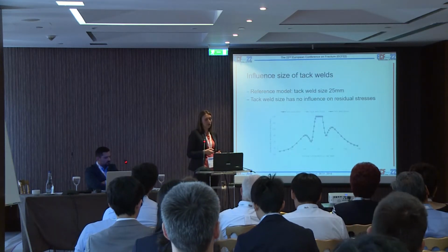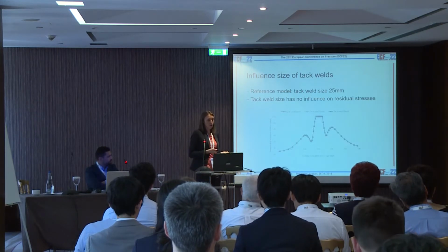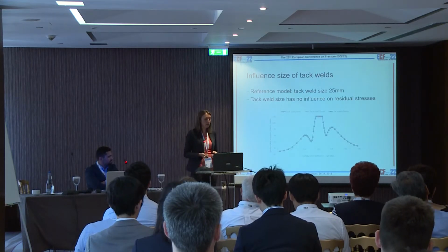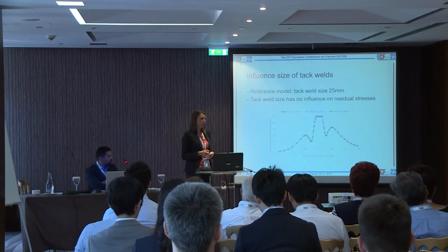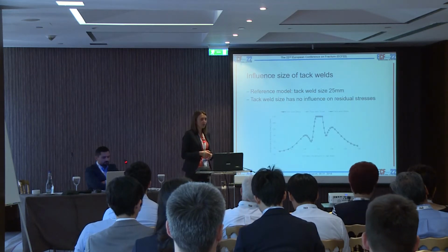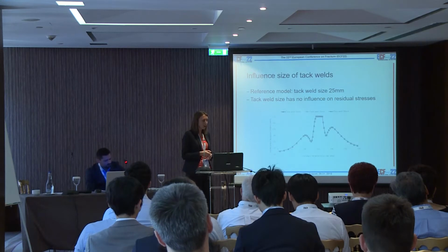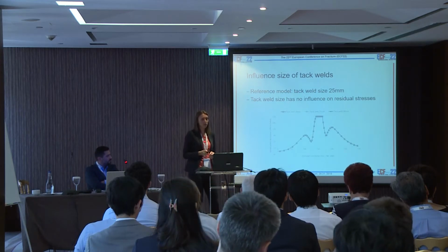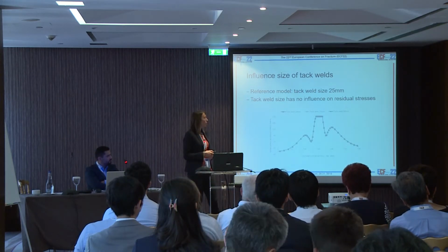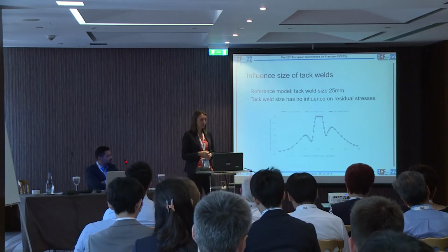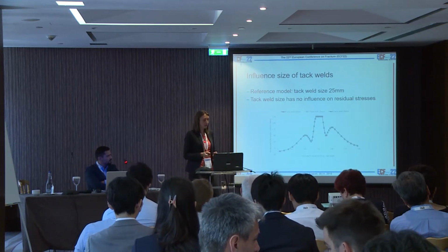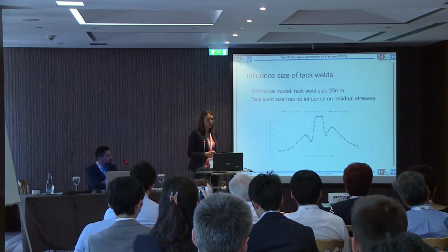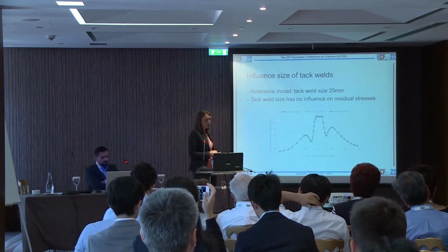Now we have this residual stress distribution from our reference model, but we want to see whether we can reduce the tensile residual stress zone in order to prevent the cracks from opening faster. So we did some variation of different parameters, and the first one was the size of the tack welds. We saw that this parameter has no influence on the residual stresses. The residual stress was exactly the same for the three different tack weld sizes that we used.